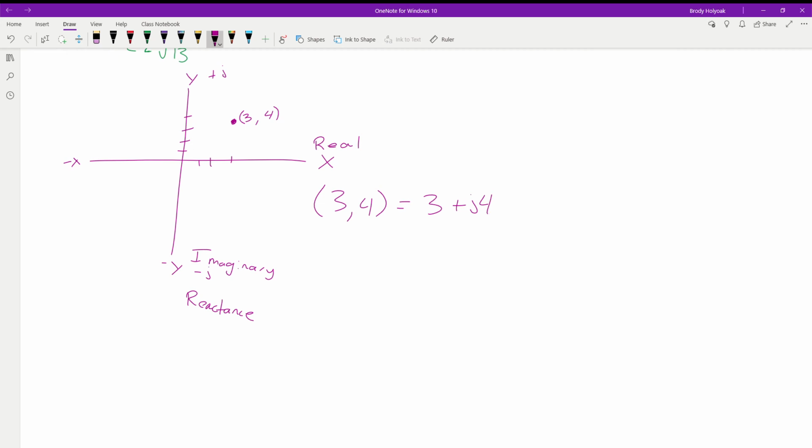So now when we have these components where we're mixing both real and imaginary parts together, we can separate what is what. What's the real part? What's the imaginary part? The other thing we could do is if we had, say, multiples of these guys. So let's say this was the equivalent of some resistance value. Okay? In electronics, we're going to call it impedance because it's a combination of both resistance and reactance. If we wanted to add these guys together, let's say we had another resistance that was 4 minus j of 3.